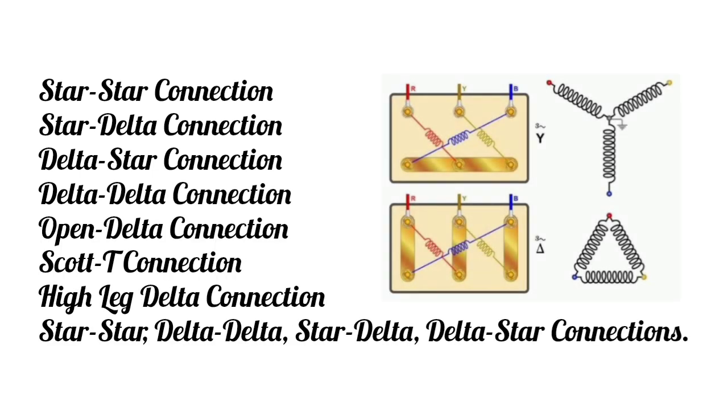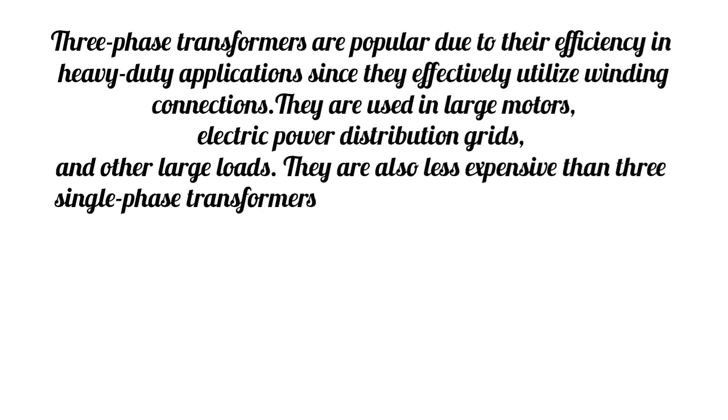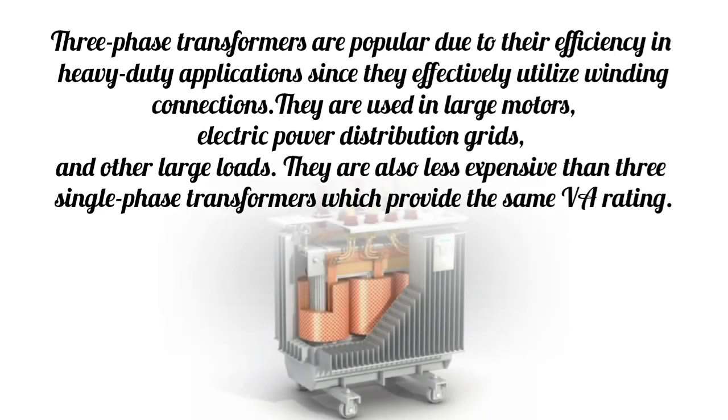Star-star connection, star-delta connection, delta-star connection, delta-delta connection, open delta connection, Scott connection, high-leg delta connection. Star-star, delta-delta, star-delta, delta-star connections. Three-phase transformers are popular due to their efficiency in heavy-duty applications since they effectively utilize winding connections. They are used in large motors, electric power distribution grids, and other large loads. They are also less expensive than three single-phase transformers which provide the same volt-ampere rating.